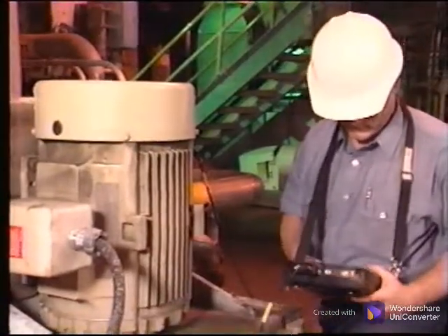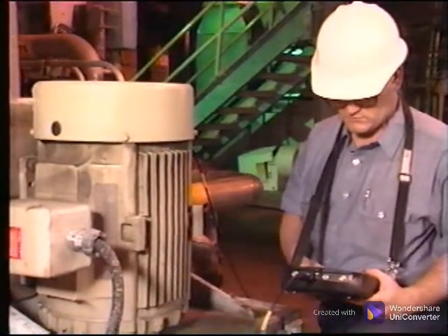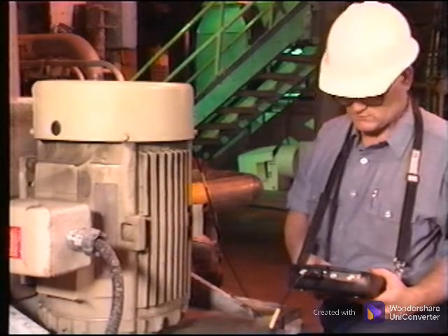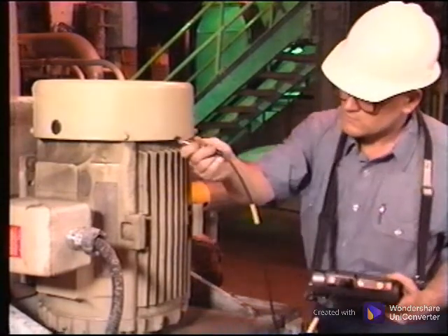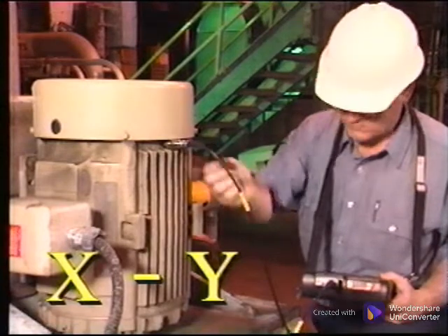Take 2 radial readings at each bearing location and at least 1 axial reading per shaft. The radial readings should still be 90 degrees apart, but should be called X and Y direction.